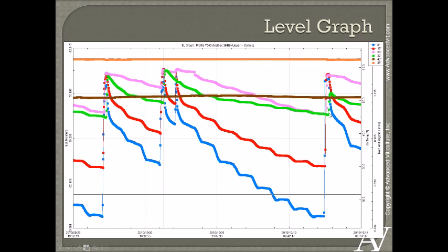But you also see, I don't know if you can see on your screen, over here this green line is a little bit shifted in time, and then actually it's a little more delayed, and it doesn't spike up as much. To me, I can read this very carefully and understand that the irrigation stopped above that level. This is the 32 inch, so it stopped somewhere maybe 28, 30 inches, and then it just redistributed down to 32 inches. It looks like a couple hours later, so that's interesting. I know exactly how far my irrigation went in each case, and that's key.